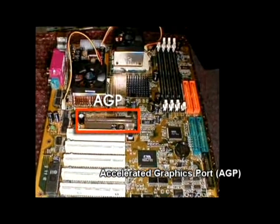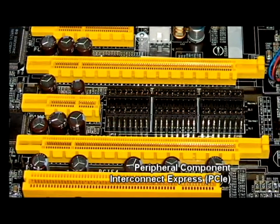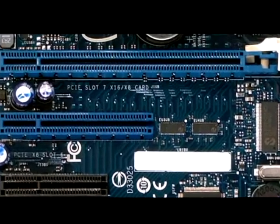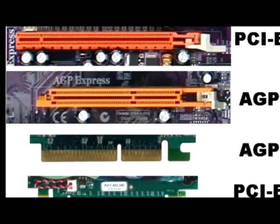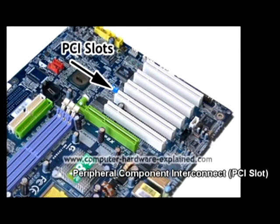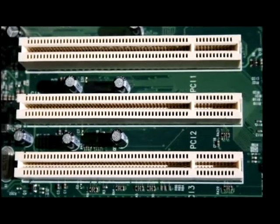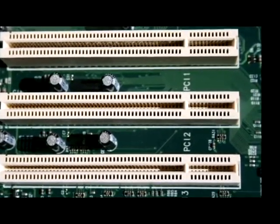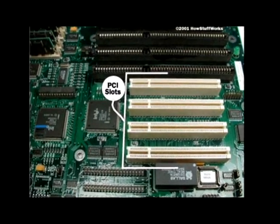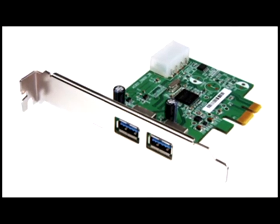Accelerated Graphics Port or AGP, and later on Peripheral Component Interconnect Express or PCIe are connection ports that are exclusive for video cards. Take note that PCIe is faster than AGP. Peripheral Component Interconnect or PCI slots are slots for older expansion cards, such as sound cards, network cards, connector cards. And these are some kinds of expansion cards we could place in the PCI slots.